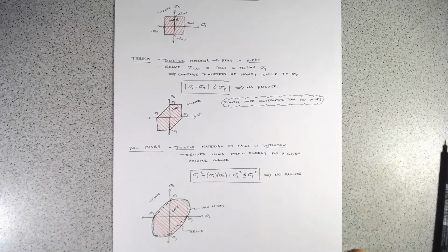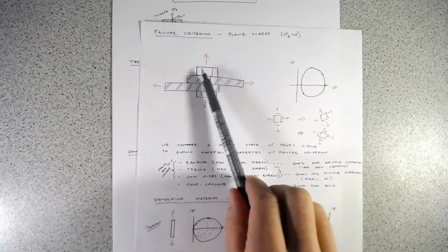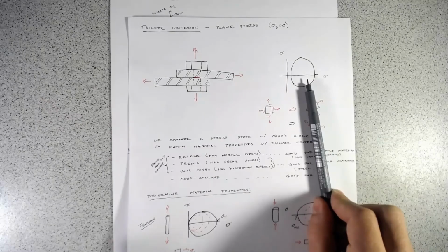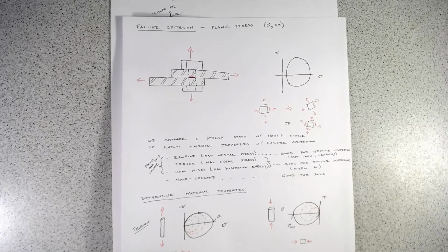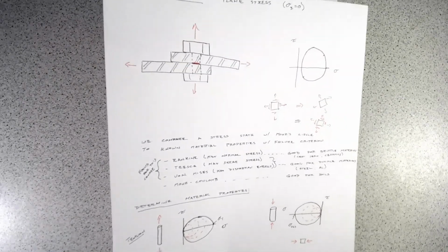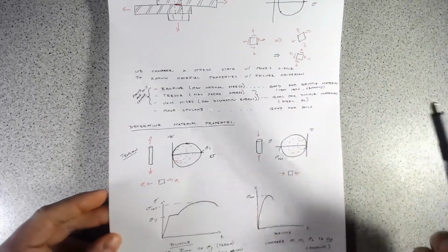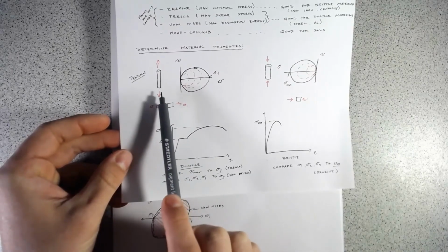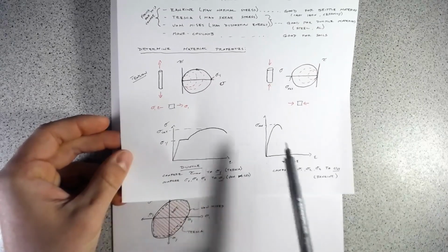But really, in terms of utilizing them, it all goes back to this notion of, we have some unknown stress state. We want to develop a Mohr circle. And then whether we've got a brittle material, which fails typically in tension or in compression, or a ductile material which tends to fail in shear, we just compare back to simple tests, uniaxial tests, to known points on there.